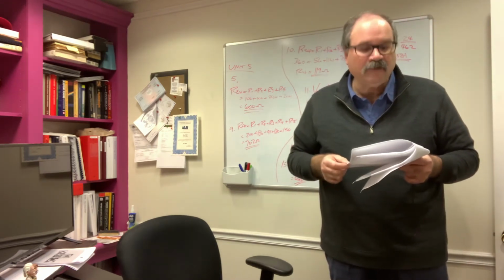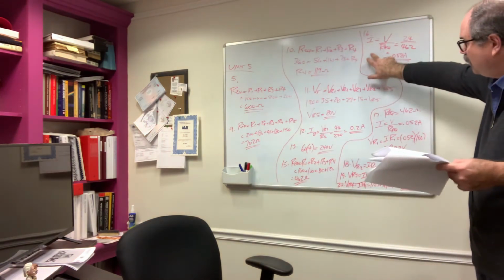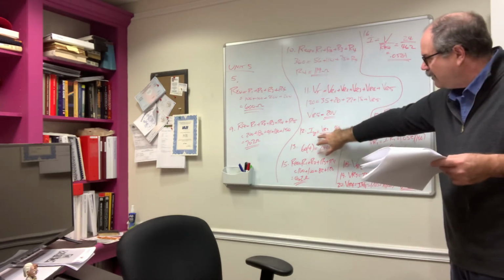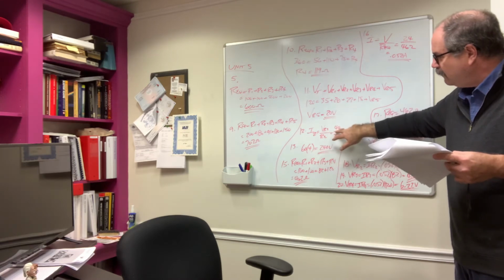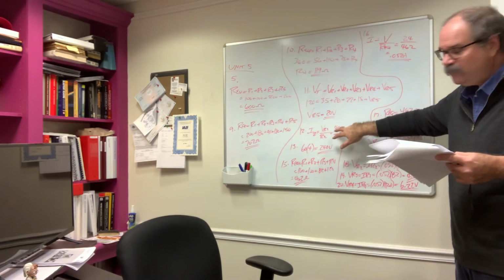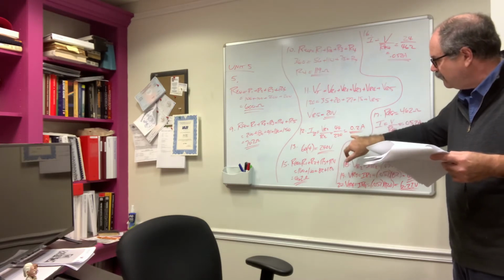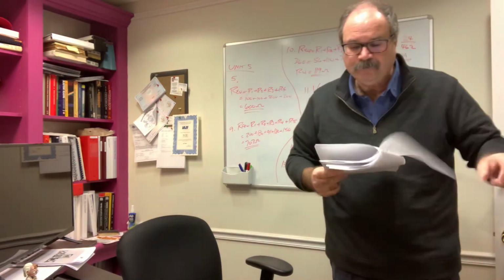So we simply have to solve for current through resistor R2. I can use Ohm's law in this example. Current is going to be equal to VR2 divided by R2. The voltage drop across that 220 ohm resistor was 44. The value of the resistor is 220. Plug the numbers in, and I get a current rating of 0.2 amps.